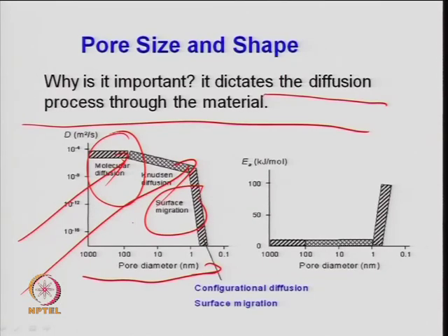So, molecular diffusion, right, generally occurs in the larger pore. Knudsen diffusion occurs in a small pore, so diffusion will be difficult. But it will dominate at high pressure or temperature, right. There are also other factors, like kinetic diameter; I said the radius of the pore is important, and the molecular weight of the gas is important. If the molecular weight of the gas is high, which is related to the diameter of the molecule, diffusion will be slow, right. For the first one, the molecules are colliding among themselves, so it will be a function of temperature, more dependent on temperature and less on pressure, right.